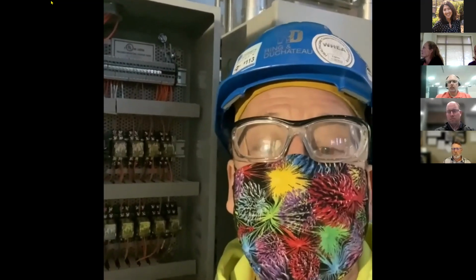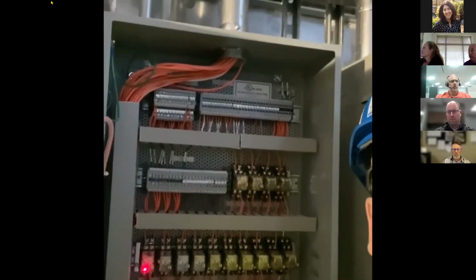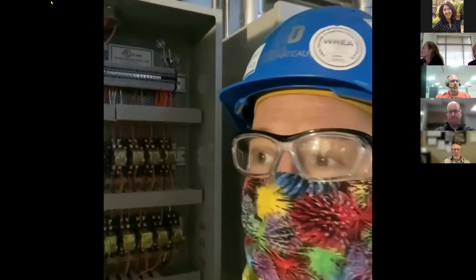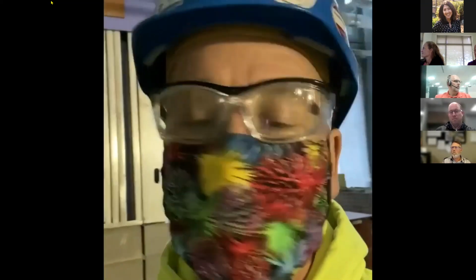So as indicated before, we're now at the same relay panel, and that safety relay that was over there is now non-illuminated, which hardwired safety shut down the air handling unit, and now the freestat element that tripped is that relay over there. I'm not going to bore you to show you on the energy management system, but I will let you know that that does work also. So in a moment here, we're going to hit the reset, but we don't let any testing go without saying, hey, what else can we look at? So we're going to revalidate that one of these 4 air handling units, when it goes off, the other 3 kind of ramp up. But we'll show you the reset in a moment.